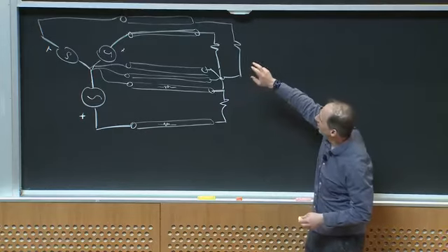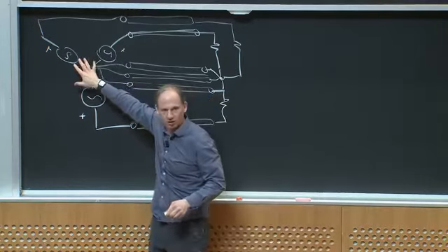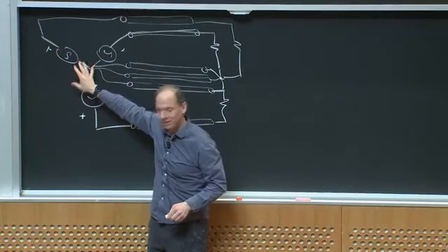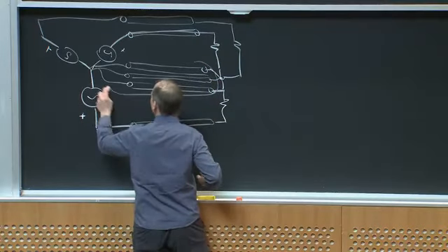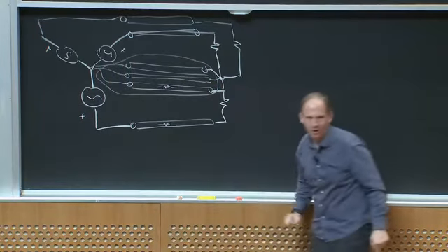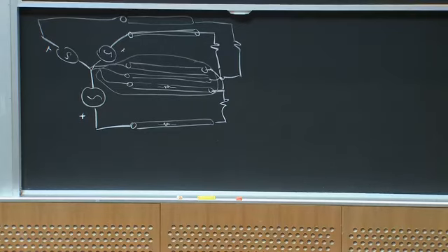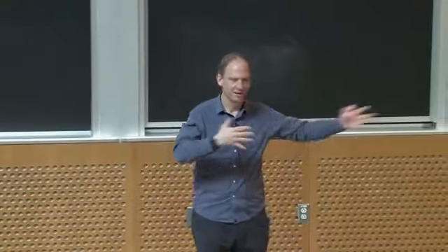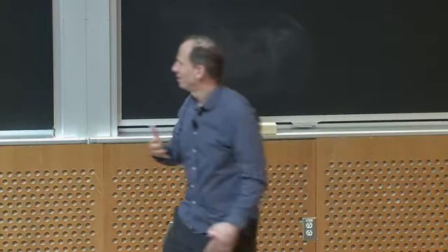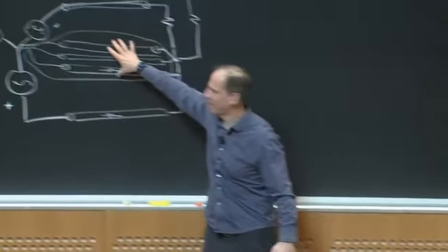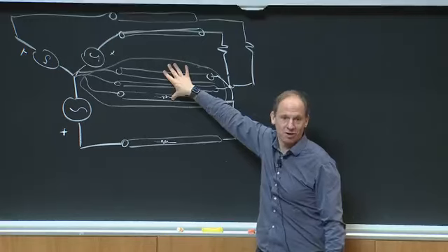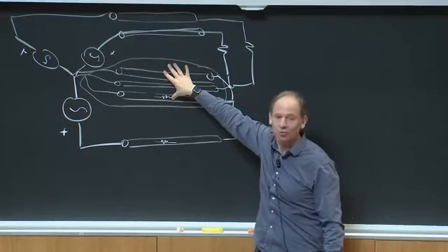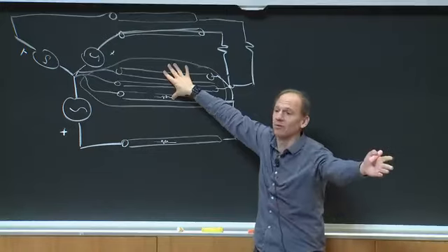But notice that all these 3 voltages and the resulting 3 currents add to 0, right? And that means that the net current in these center conductors is what? 0. So suddenly, if what I cared about was the copper loss to send power down the line, I can basically throw away half of my conductors for a 3-phase system instead of a single-phase system. I need half the copper to carry that much current, okay? And that is a huge advantage if your goal is to transfer power over long distances.